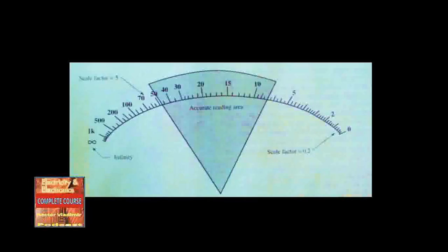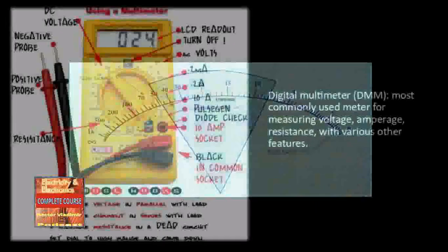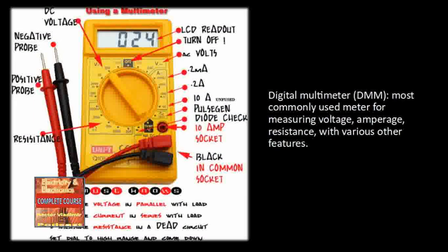Often, electronic circuits are quite compact. Be sure that the test leads do not cross over 2 or more connection points, as this could result in a short circuit. Be sure that the test leads are in good working condition. There should be no frayed or bare wiring. Make it a habit to keep your fingers from touching any exposed metal part of the test lead tips and/or the circuits being tested.